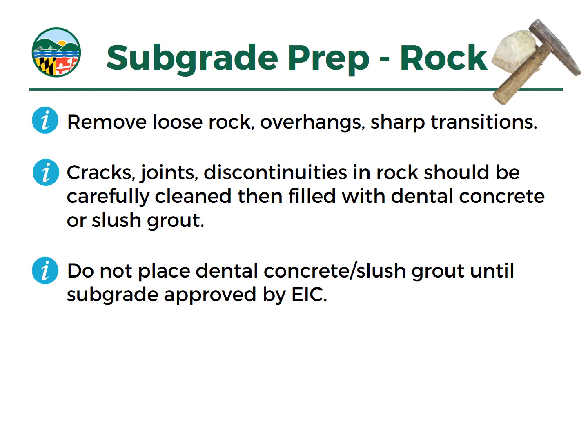So with a sharp overhang or a sharp transition, when you're placing soil into there and you don't have good compaction control, which sometimes is not the contractor's fault, it's just a geometry issue, you can get lower stress areas in the soil or differential stresses. And differential stresses lead to differential settlement and cracking, and most people have heard of differential settlement before. They know it's a bad thing. And of course, cracking in a dam embankment can lead to all sorts of problems. So again, keep that subgrade nice and even, remove any of the loose materials,